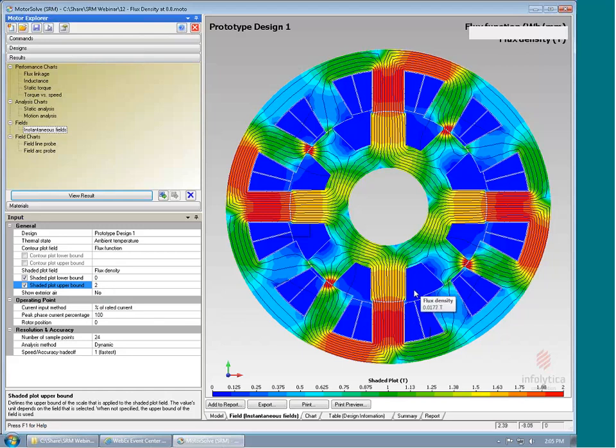And you can see here that we have quite a few places of symmetry in the machine, which you would expect. We have places where we have very high flux density. We have places where we have very low. Again, with the rollover, I can see that my flux densities are on the order of 2 Tesla, implying that for this short instance or instantaneous time, that this area of the steel would be saturated.